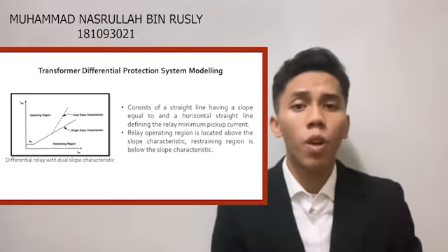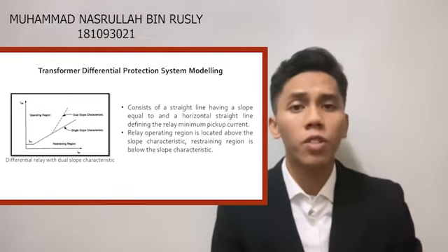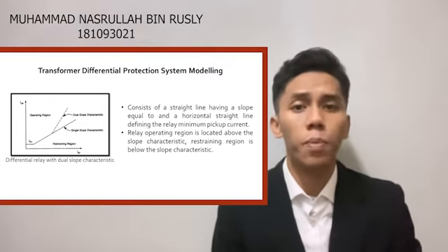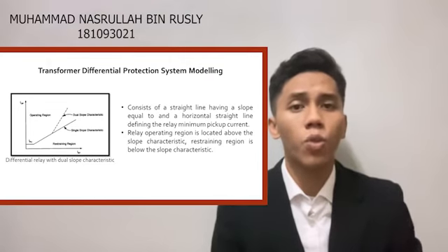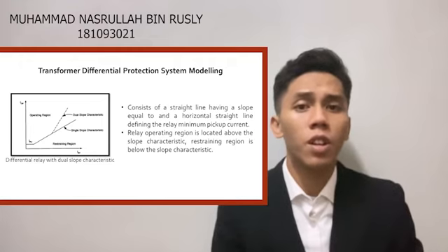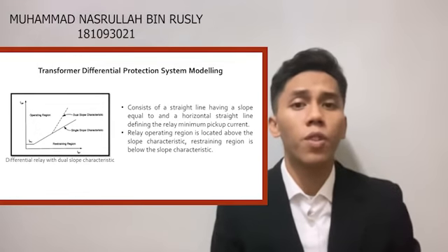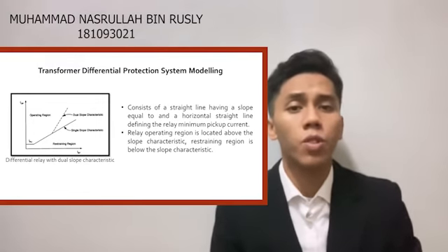Differential relays perform well for external faults as long as the current transformer reproduces the primary current correctly. When one of the current transformers saturates, or if both current transformers saturate at different levels, a false operating current appears in the differential relay and could cause relay misoperation. Some differential relays use the harmonics caused by current transformer saturation for added restraint and to avoid misoperation. In addition, the slope characteristic of the presented differential relay provides further security for external faults with current transformer saturation.